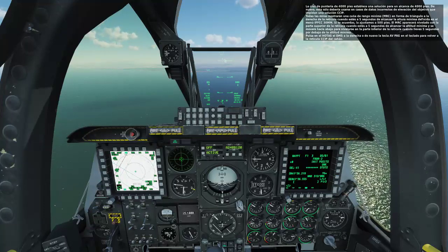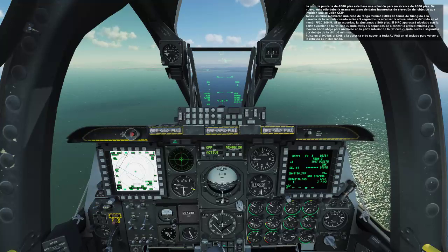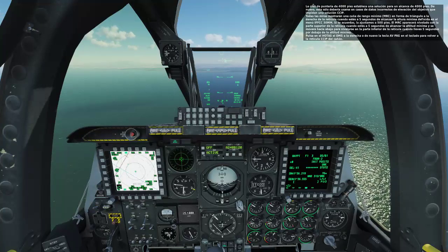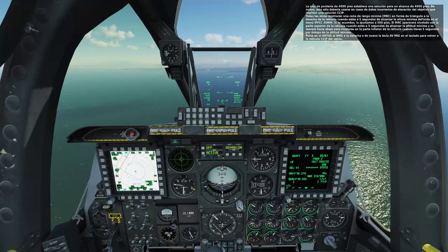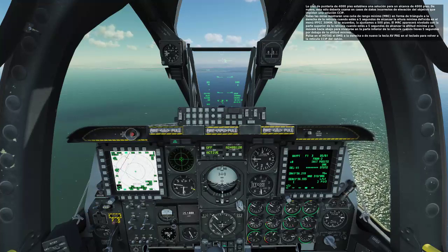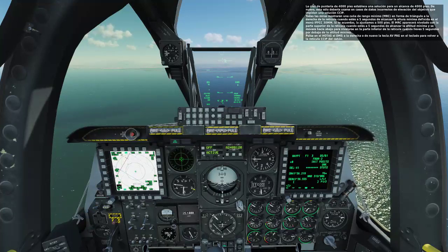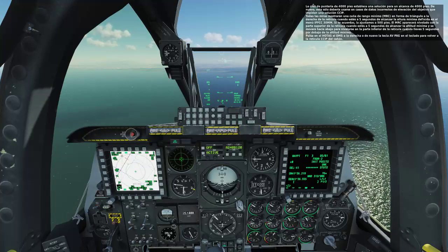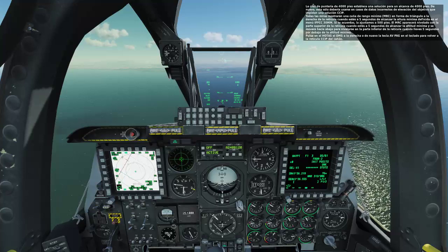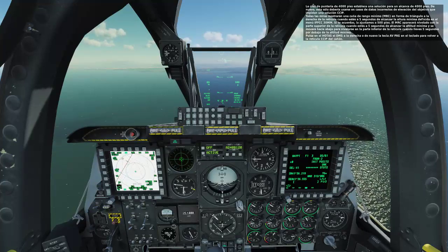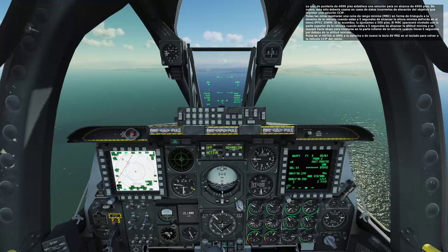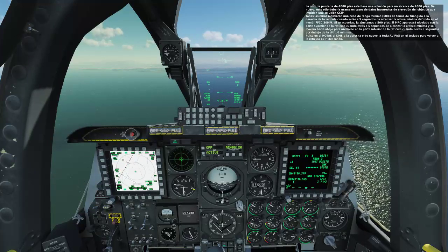The 4,000 foot gun cross preset is a gun solution for a range of 4,000 feet. Once again, this would normally be used only in cases of inaccurate target elevation data preventing a CCIP solution. All gun sights will indicate a minimum range cue as a triangular index to the right of the reticle when you are within 5 seconds of the minimum altitude set in the IFC 30mm menu. If you recall, we set this to 500 feet.